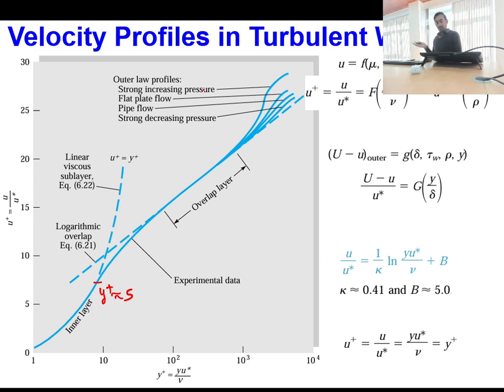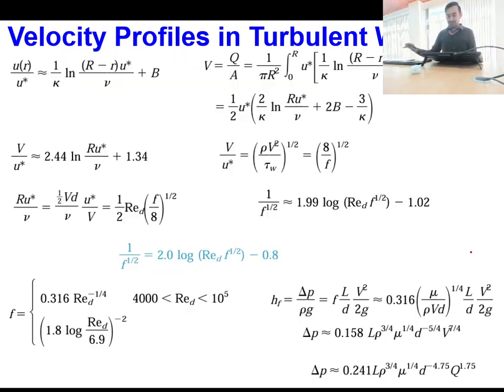So we will make an assumption that for the entire boundary layer zone across the wall, we have nothing but the logarithmic variation of the velocity field. By using this logarithmic law, we will try to deduce the velocity field, the corresponding wall shear stress, and then determine the relation of friction factor for turbulent flow conditions. We can see that in the subsequent discussion.